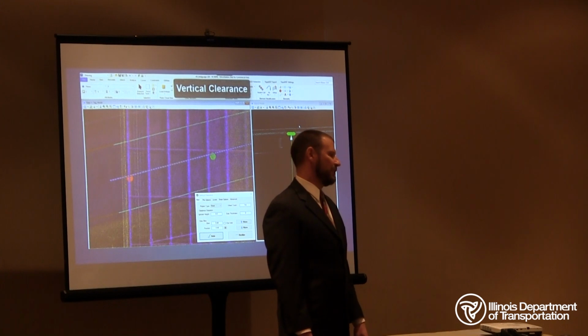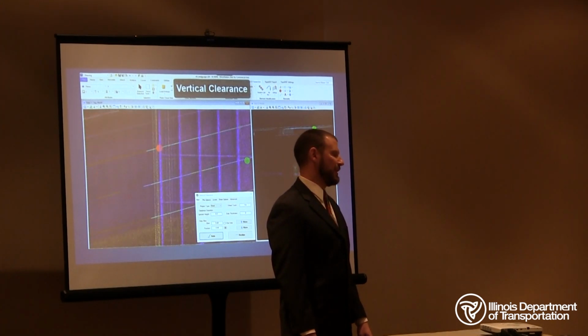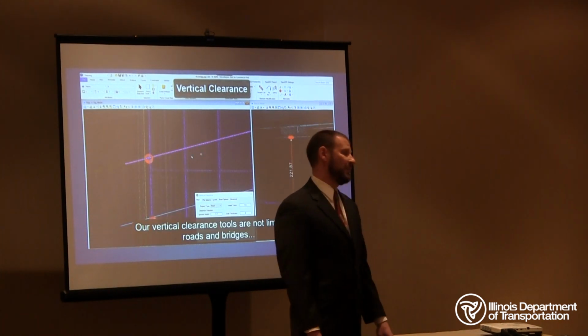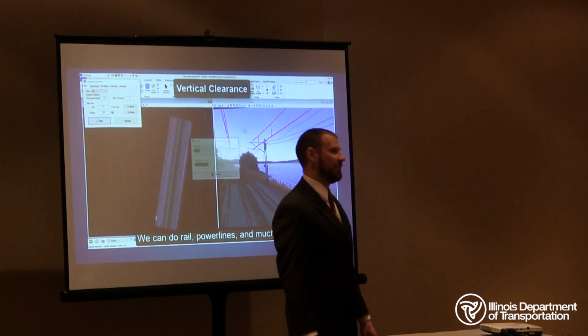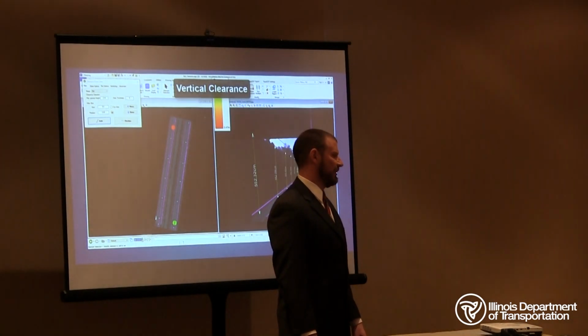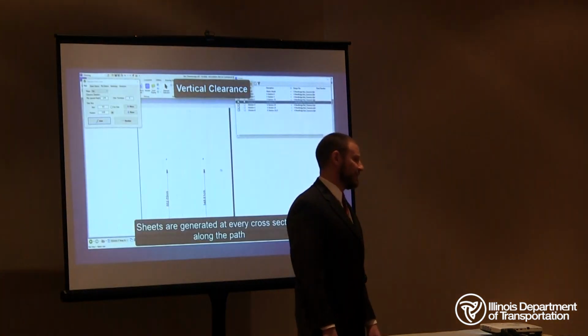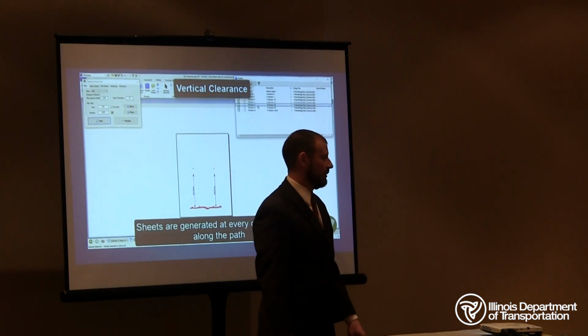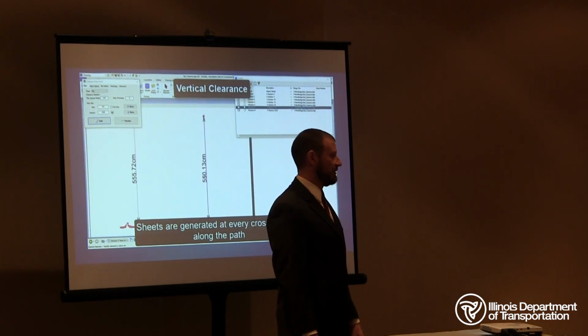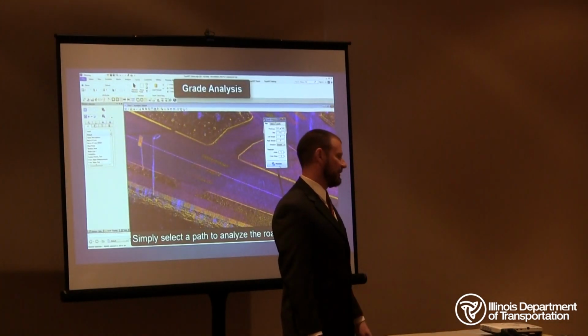And then it zooms into those areas to show you what it's measuring to in that point cloud. So you know exactly what you're getting. And from what I'm told, you can actually extend out a plane to account for the sag situation with the truck going underneath. In our district, we have done some terrestrial LIDAR scans to establish the elevations of wires relative to the pavement. This is a quick analysis tool for that.